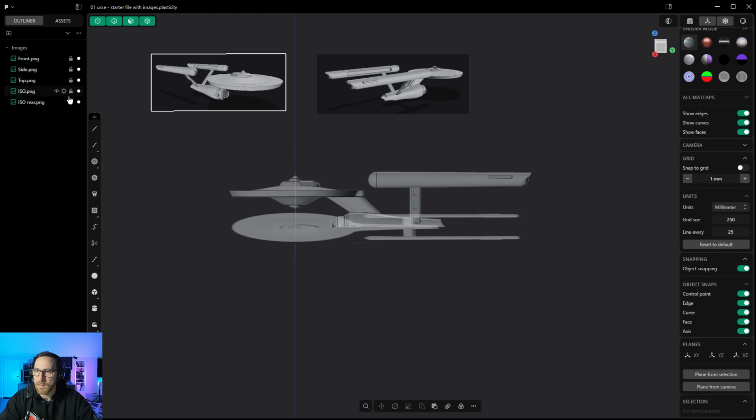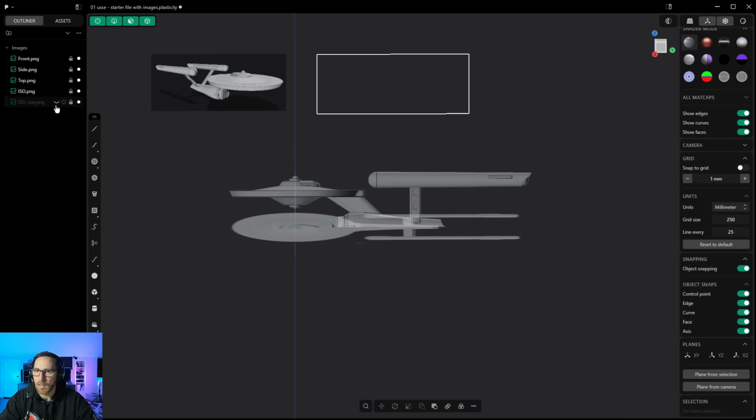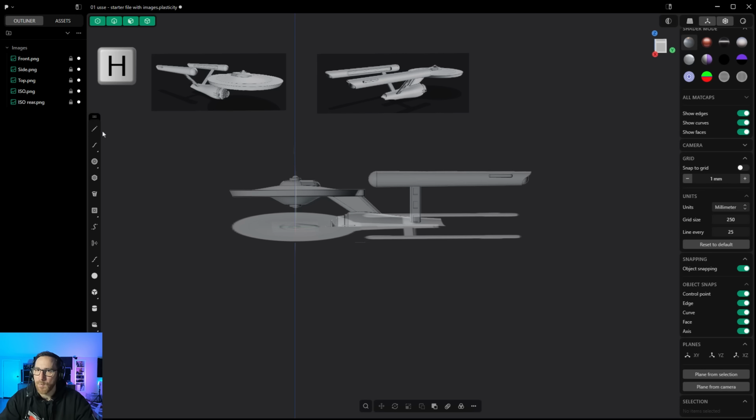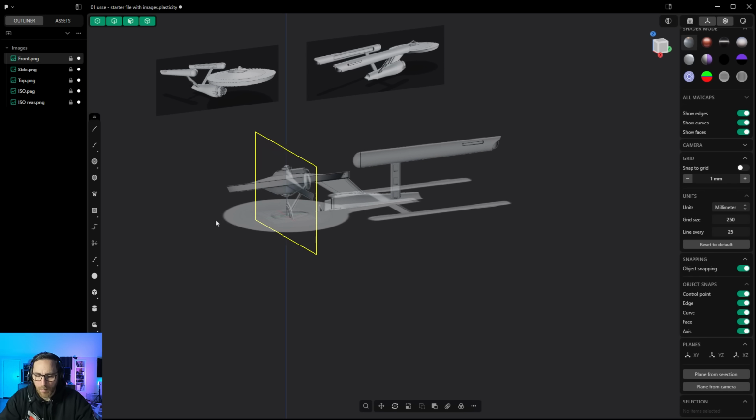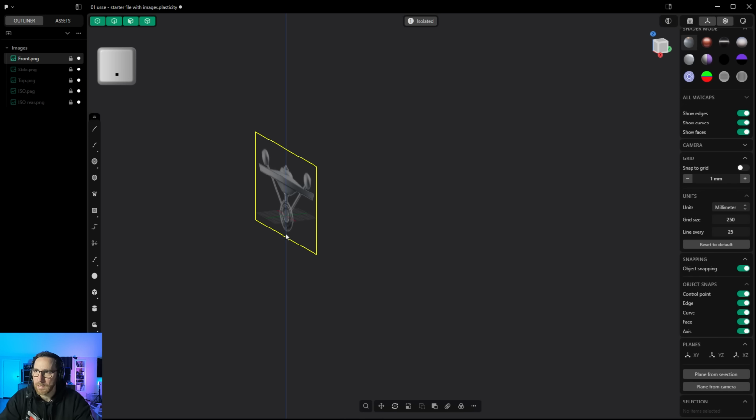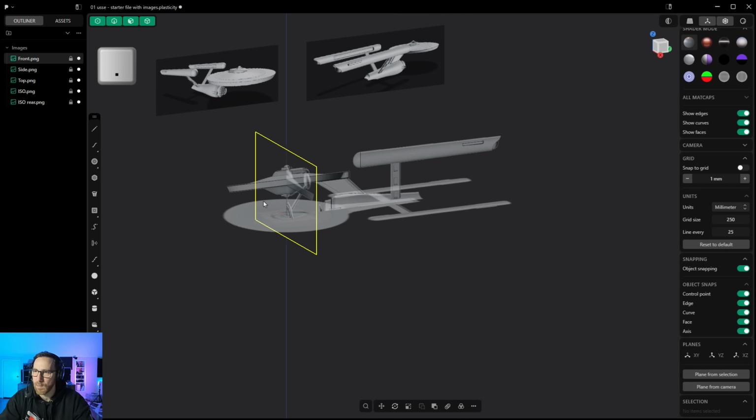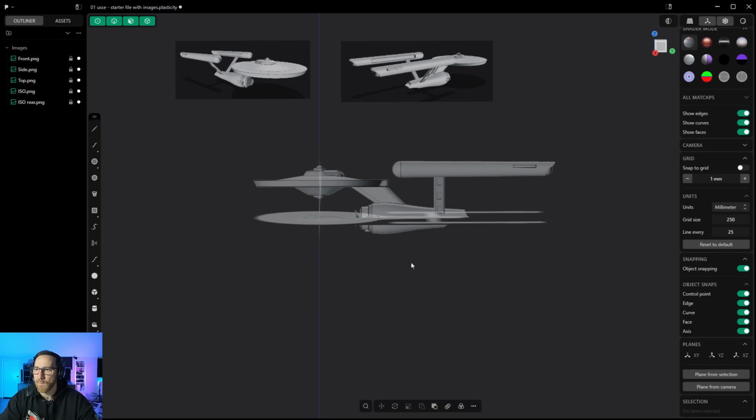These are all locked. The opacity has been reduced on all the ones that we need, and you can change the visibility by clicking on the eye icon, or if they're selected, you can hit H, which will hide them. And if we happen to be working on one object, you can hit the period key, which will isolate it, and then if you hit period again, it'll bring everything back. And so now that we've got all these references in here, we can get started modeling.